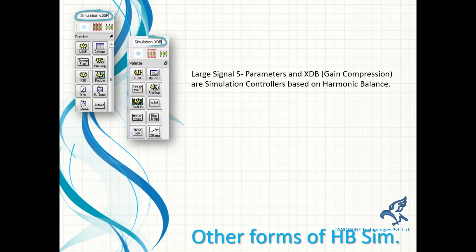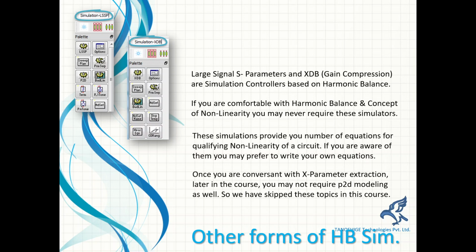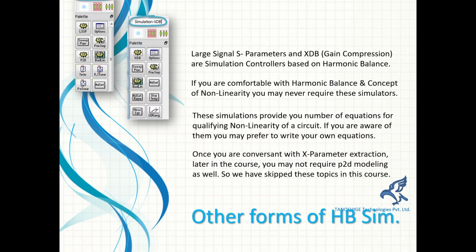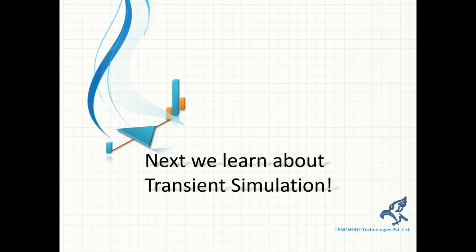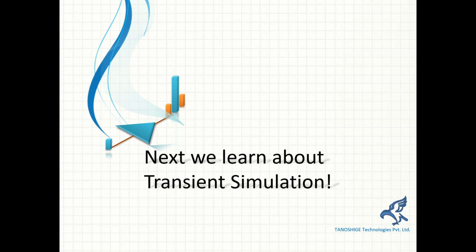Okay, so we are looking at large signal parameters, gain compression and other stuff. We will look at the accelerometer in a separate session. Okay, so we are going to do a harmonic balance simulation of the same stage, and then we are going to plot the output sweep versus the input power, right?